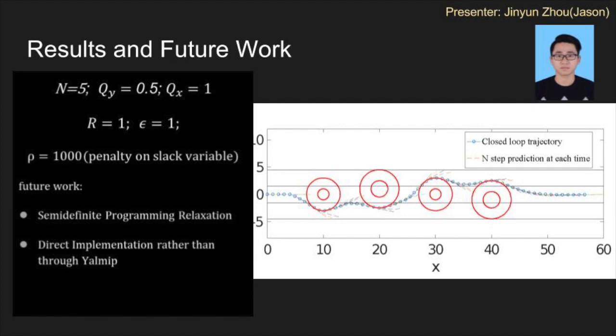The prediction horizon N is actually a key parameter in our design. If N is too large, the computation time is too high. If N is too small, the truck's reaction to the obstacle is too late and would cause the truck to be unable to avoid the obstacle cleanly. When N has the value of about 5, 8, and 11, the average computation times are about 1.5 seconds, 4.2 seconds, and 9.3 seconds. So clearly the computation time is a huge problem here, and some improvements should be made in future work.